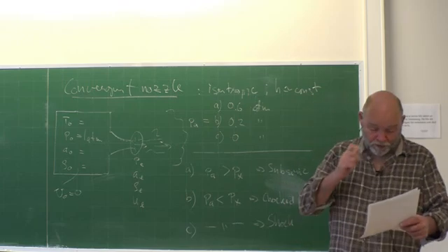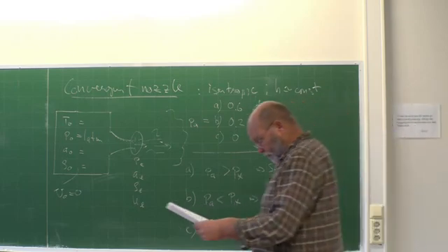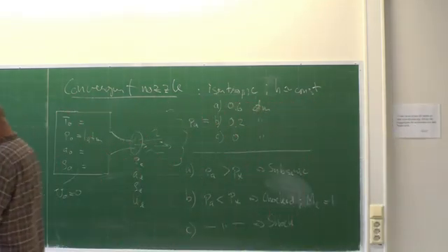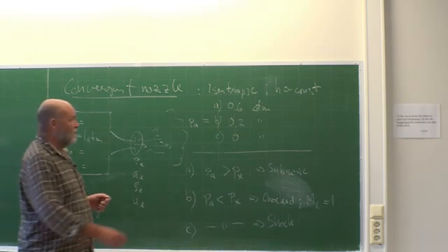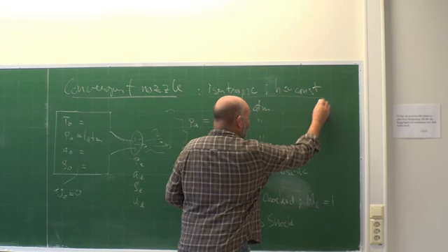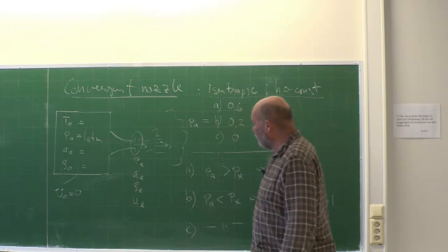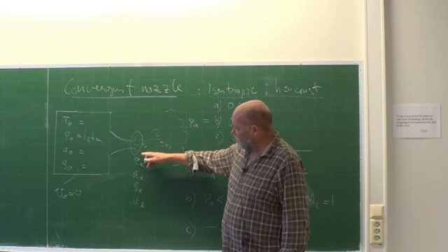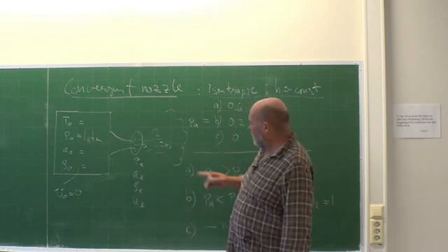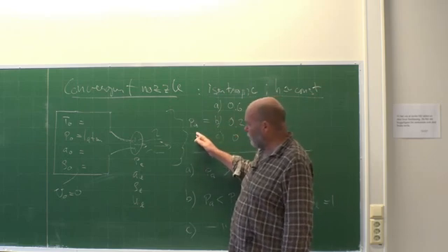We are going to get shock waves. And when it comes to shock waves, or actually expansion waves, then you can't use the theory anymore, because it is not valid through a shock. So you're going to need some expansion waves, because the exit pressure here is so low that it doesn't match whatever reservoir pressure we have on the outside.